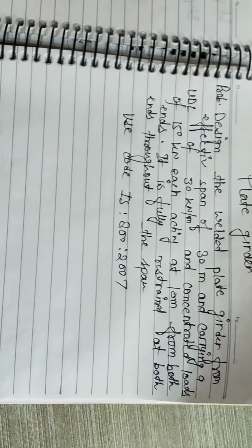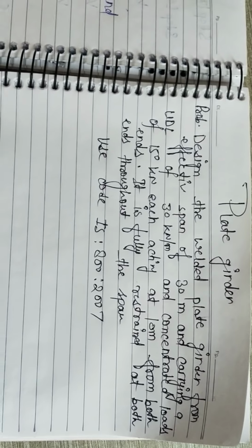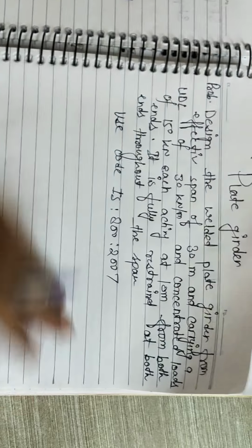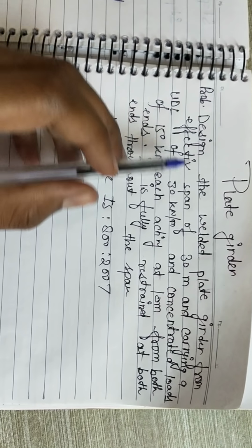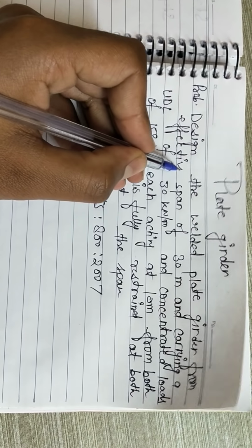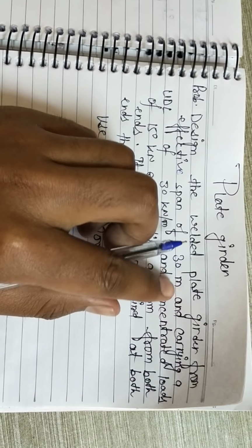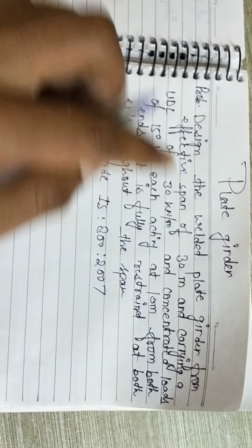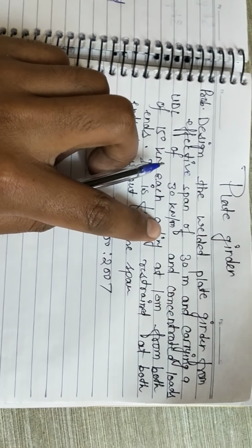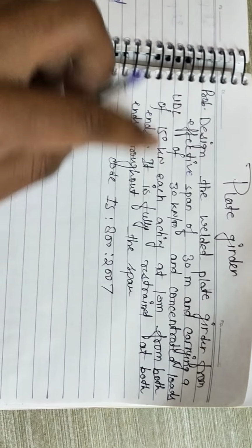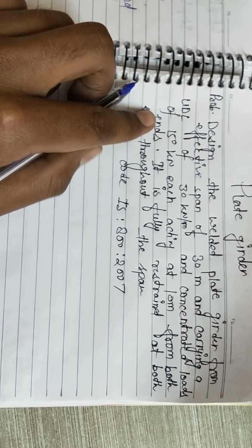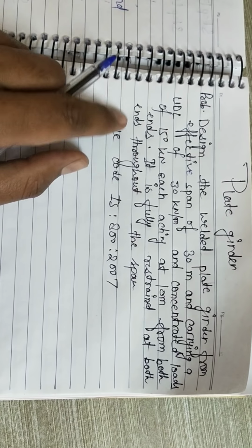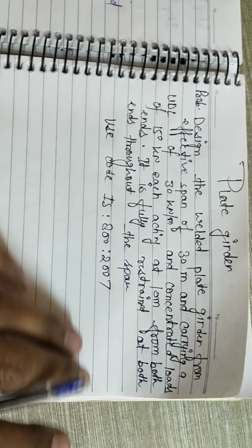As I promised yesterday, I will make a video on plate girder. This is a numerical video of plate girder. So let's explain the problem. Design the welded plate girder for an effective span of 30 meter and carrying a UDL of 30 kN per meter over all the span, and a concentrated load of 150 kN is also acting at 10 meter from both ends. It is fully restrained at both ends throughout the span.